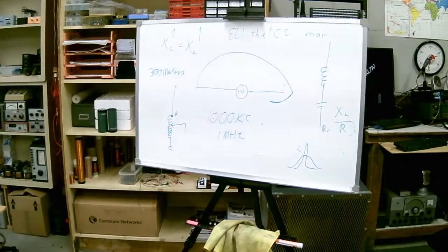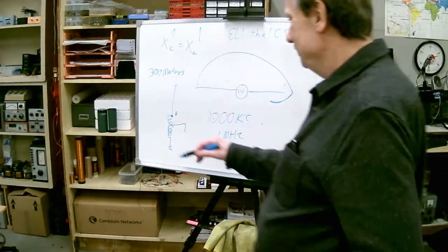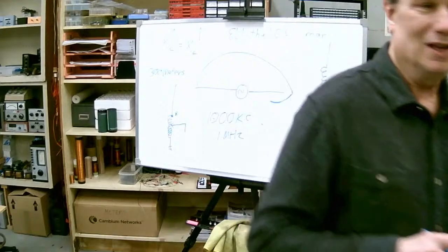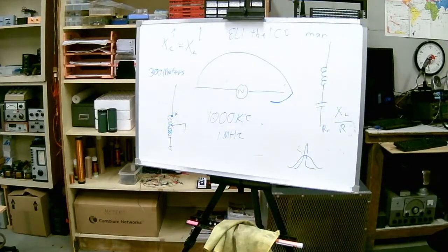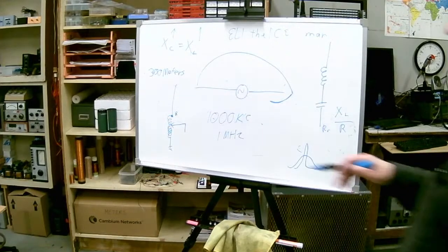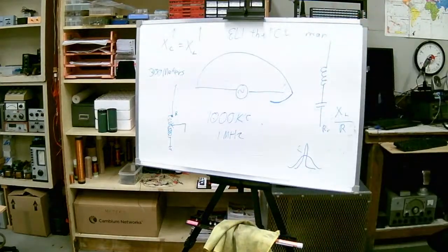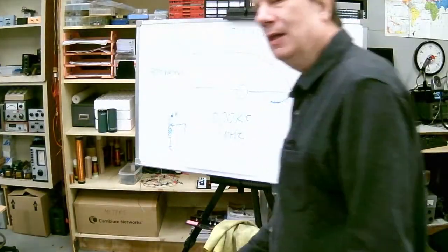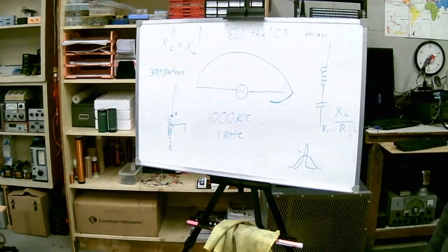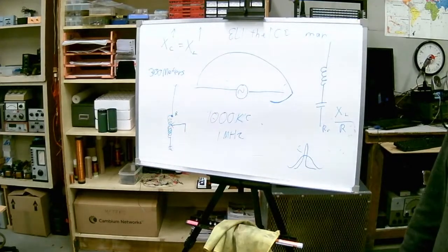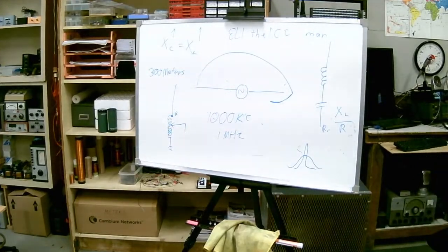Now, if we didn't have a loading coil, we would no longer have a high Q circuit, but we would have a very lousy circuit to start with. So the sensitivity would be nothing, so we resonate this, so we can get some actual power out of it, and then we can match that, and then use a tuning of the front end. Again, what we're putting there is an inductor, like a variable inductor. It's got a slug tune inductor. We'll take apart some car radios at one point here.